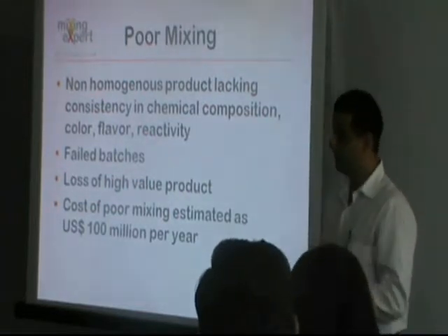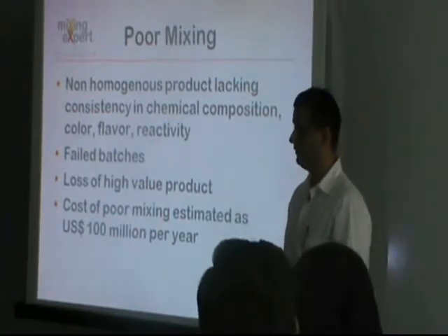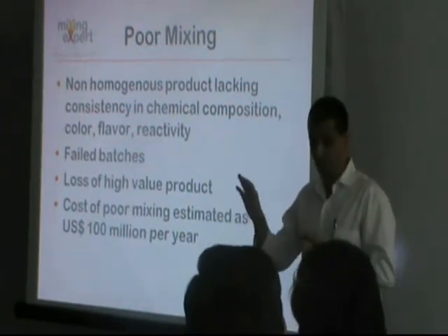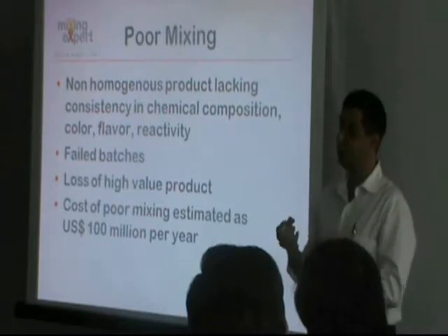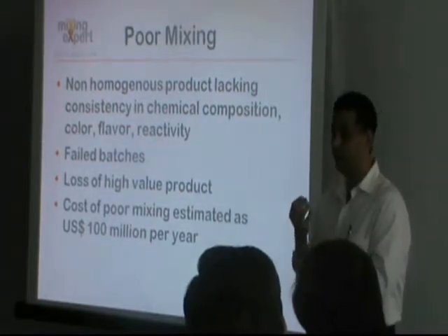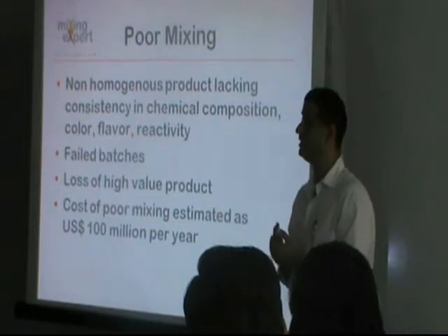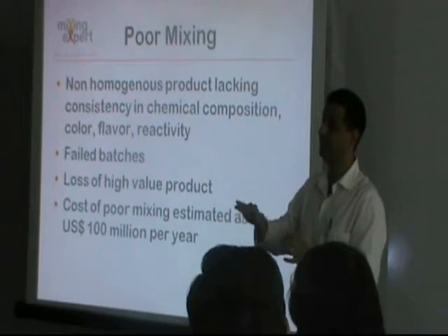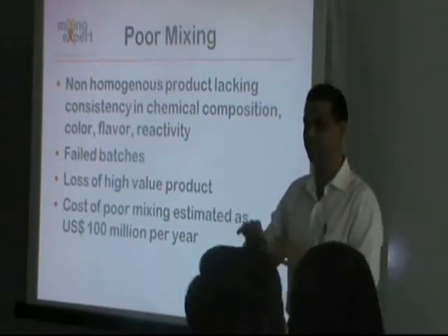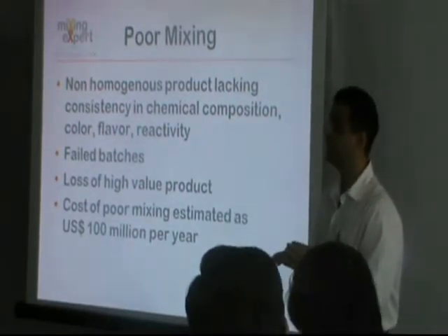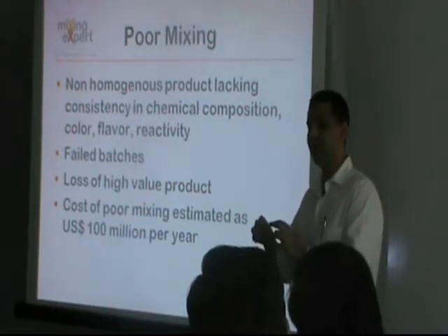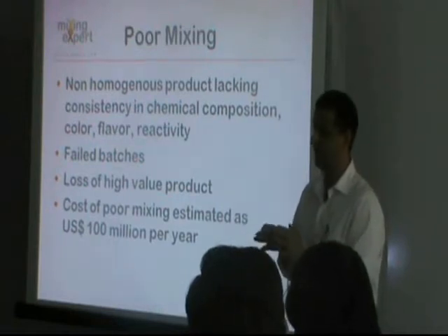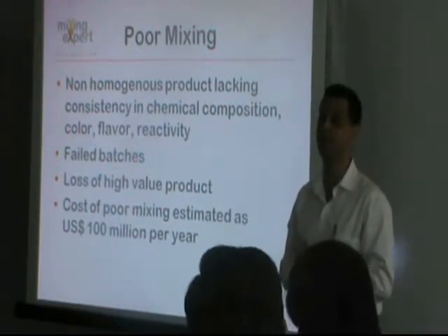There is also a difference in the extent of homogeneity when it comes to solid mixing and liquid mixing. Because in liquid mixing, when you draw a sample, the level of homogeneity that you get is far greater than what you would get in what is defined as a well mixed solid sample. Because depending on the blend structures, depending on the material properties, the levels of acceptance in the case of solid blending are less as compared to what is expected in the liquids.